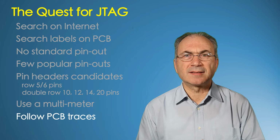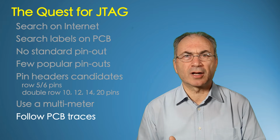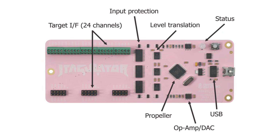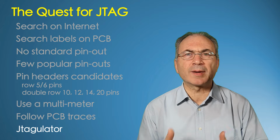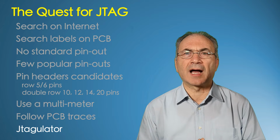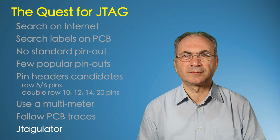The best and easy solution, once we have identified potential JTAG pin candidates, is to use Jtagulator. Jtagulator is a fantastic tool. It has a lot of headers that we can attach to potential JTAG pin candidates, and then it can run some automatic scanning logic and can identify the JTAG pinout. Later we will see how to use Jtagulator.